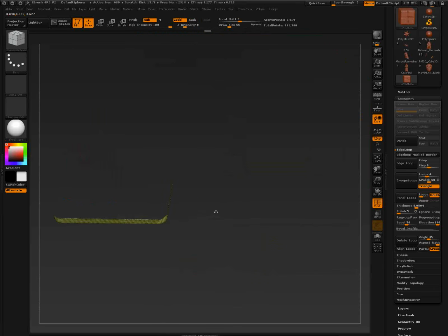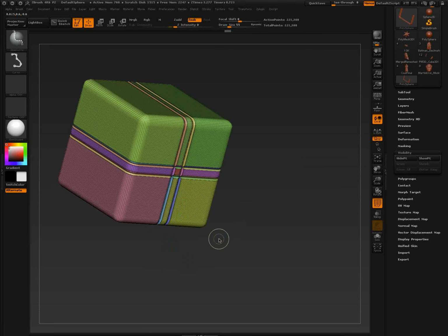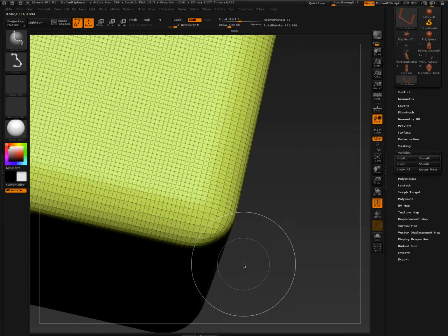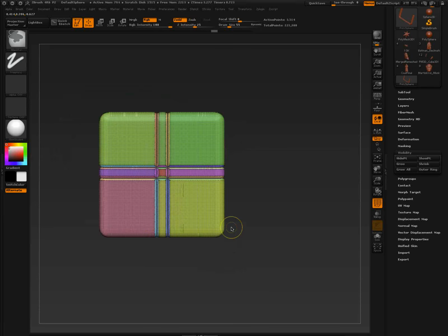When I just click on the polygroup, I'm only getting an outside polygroup. And I hit Control-Shift-A, as in select all or grow all, which is in the visibility section right here. You got grow all. Because I have a little portion selected, we can even get as crazy as selecting one face or a couple faces. And I hit that Control-Shift-A and I get that whole bottom portion. Very cool to be able to do this. I use this a ton.